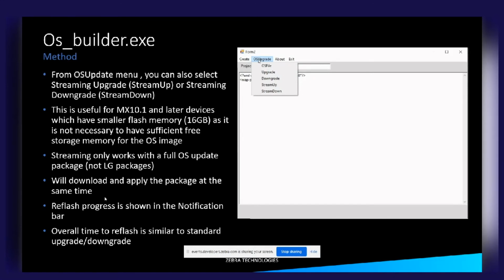So you have one active partition, one backup partition. The streaming image goes into the backup, and it's only when it's completed streaming the full image to the backup that it switches from the main to the backup partition. So it's basically been designed to be fault tolerant, and it will still reboot with the existing image if you have a failure when you're streaming the new image.